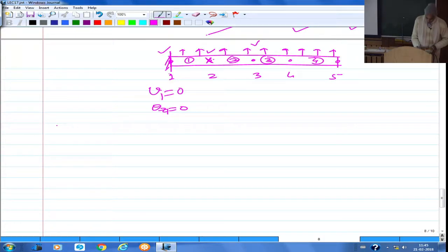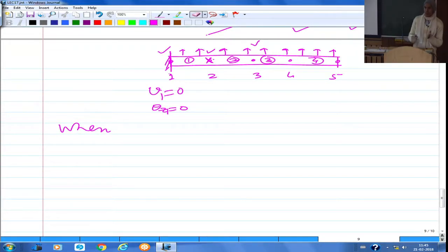Timoshenko means, later we would generalize, shear deformable. What is the meaning of shear deformable? It means the transverse shear deformation is allowed. We are removing the constraint of the normal remaining normal to the deformed centroidal axis. In this case, the Timoshenko beam finite element is a shear deformable finite element.